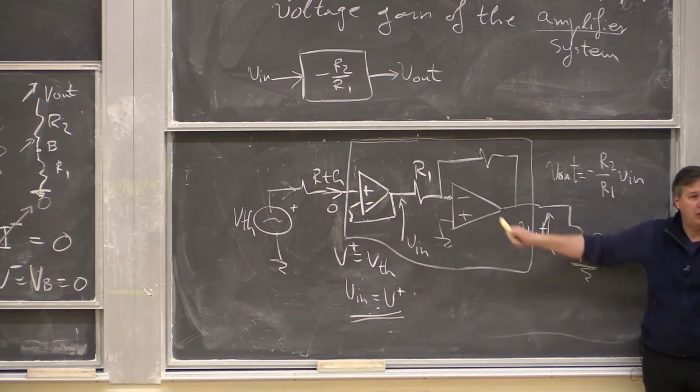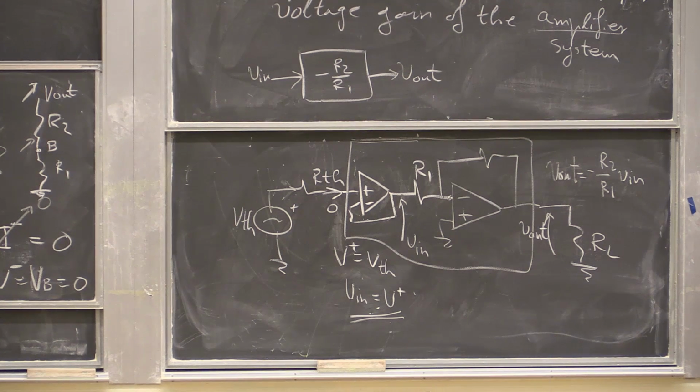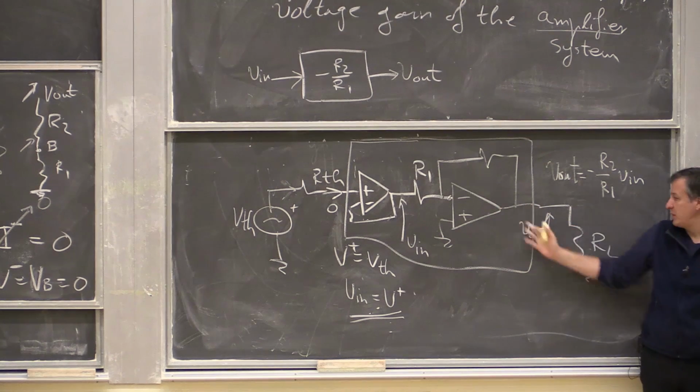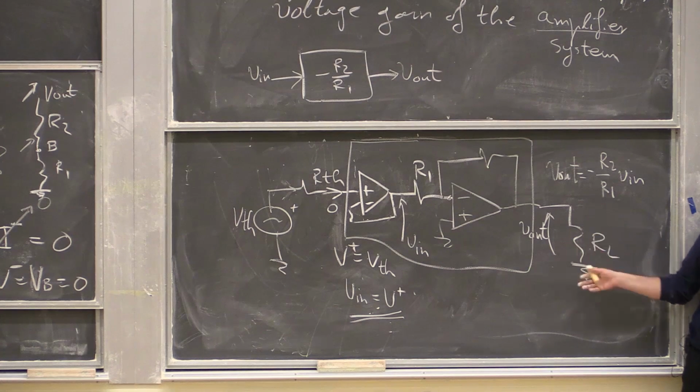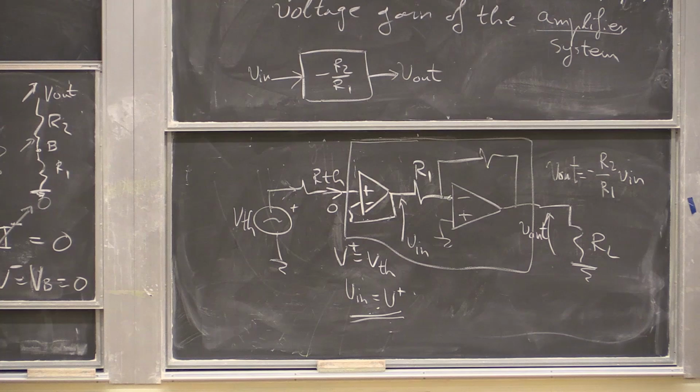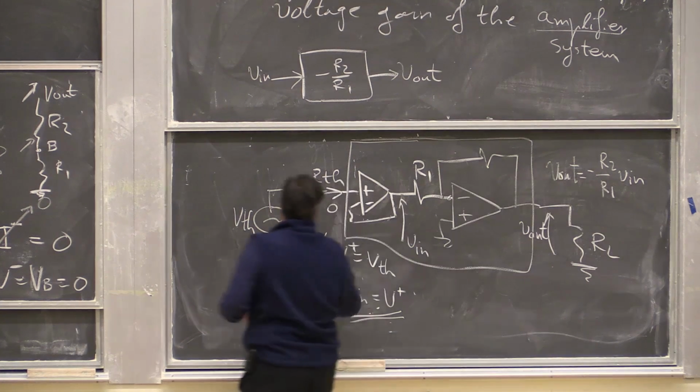Think about what's the equivalent model of the op-amp. What drives the output of the op-amp? Yes? Yeah, A times V error, right? The voltage-controlled voltage source. Well, a voltage-controlled voltage source doesn't care what load it gets loaded with, right? Whatever current it needs to supply it just happily supplies, as long as it enforces the desired voltage, right? Therefore, the output that this op-amp will produce is not going to depend on anything you attach to it. Right? You can attach 1 kilo ohm, 1 ohm, whatever. That's how we were able to drive the loudspeaker last time, because the op-amp can provide enough current drive, even into a few ohms of resistance. Does it make sense? So the key concepts here are, there's isolation here.